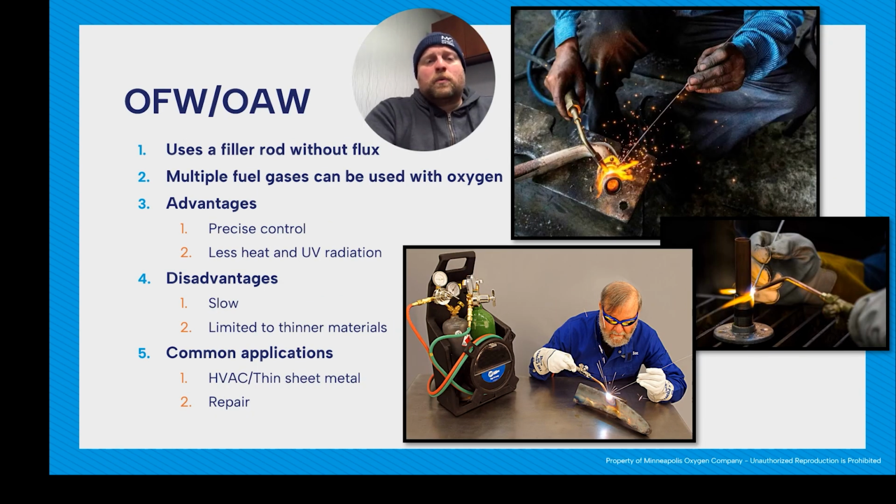Lastly is oxy-fuel welding or oxy-acetylene welding. I included this not because there's a ton of people who do it, but at least in our world, we have a lot of HVAC companies that will use this to help supply materials, industrial gases, that sort of thing. And they do a decent amount of oxy-fuel welding. This is also similar to a brazing or a soldering type application. The main difference between soldering, brazing, and welding is the temperature at which they're done. Soldering is a lower temperature, brazing is medium, and welding is high temperature.